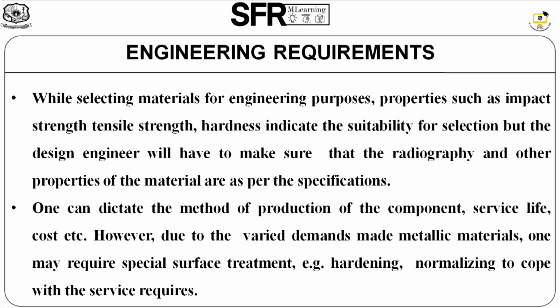Though inferior to most metallic materials in strength and temperature resistance, these are being used not only in corrosive environments but also in places where minimum wear is required. For example, small gear wheels which were originally produced from hardened steels are now manufactured from nylon or Teflon.